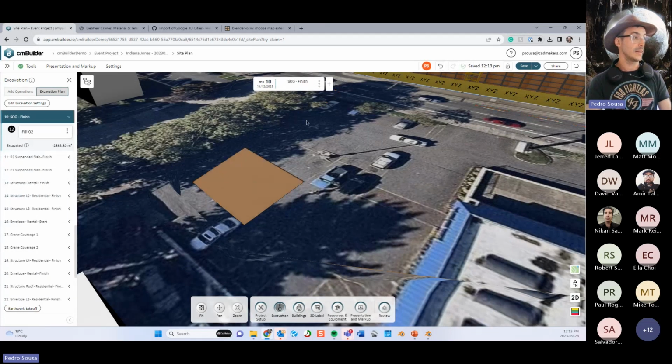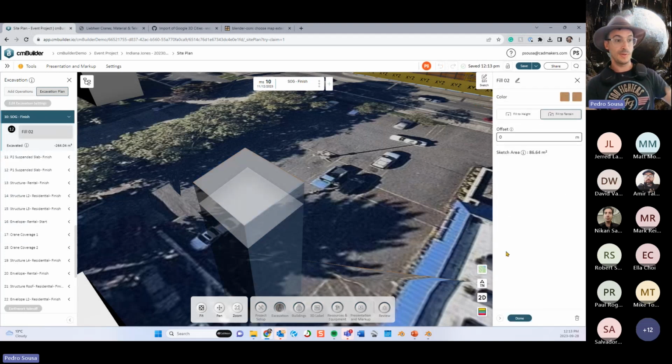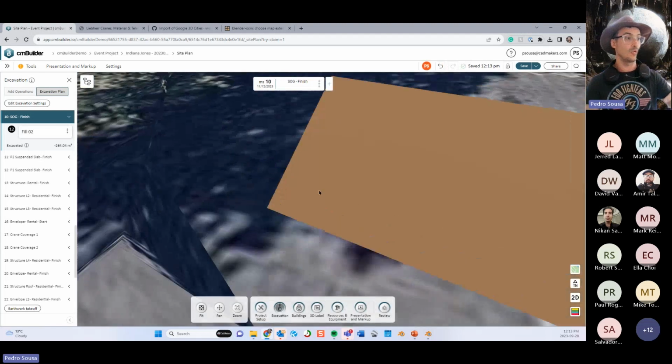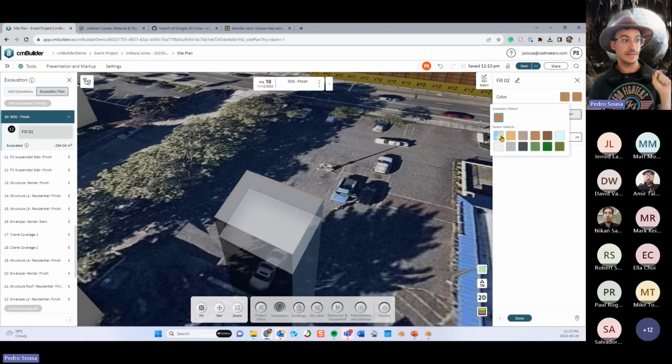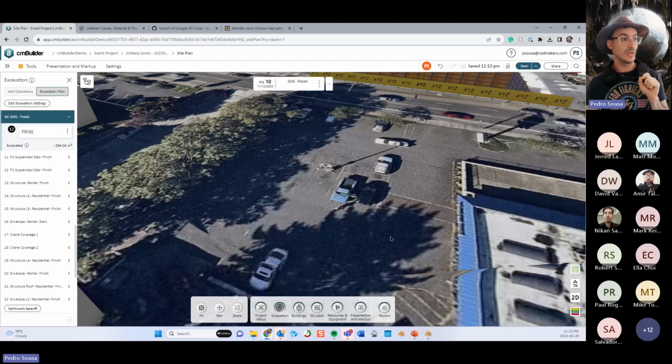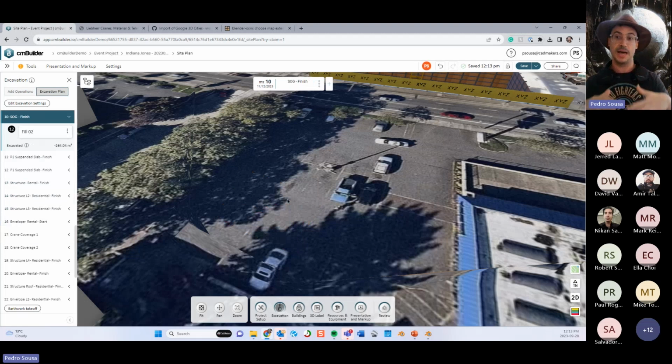And then the difference is that now, with this fill in here, I can do the fill to terrain. So it will bring my cut back to the original terrain. But also I can click on this and make that fill look like the map. So this will apply the same texture that is in the map to that fill. So whenever you do a backfill, you won't need to manage the colors with workarounds. You can do it directly from the excavation tool just by assigning the satellite image and whatever is projected onto the fill.